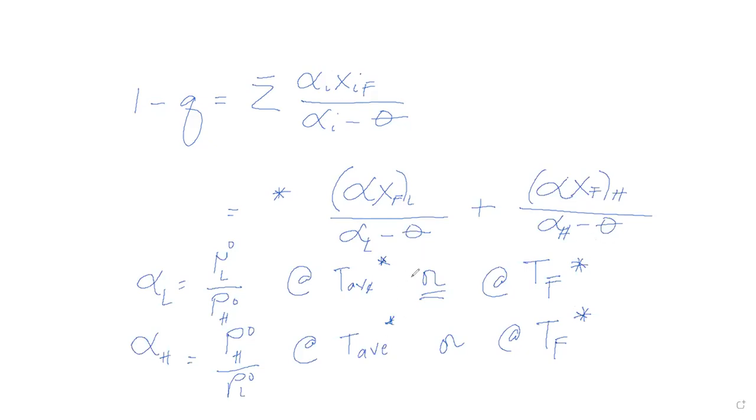If the boiling point equilibrium diagram for your system is not given, especially if it's not benzene and toluene, then they are not readily available. Then use this one. You just use the temperature of the feed as a basis in determining this. You get this in section 2 of your handbook, the pure vapor pressures of the low boiling point component and the high boiling point component. This is an option of finding the alpha.